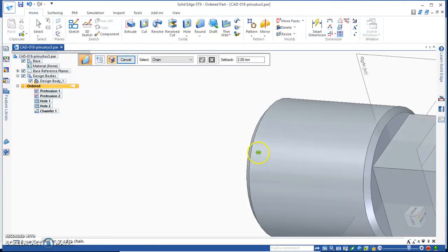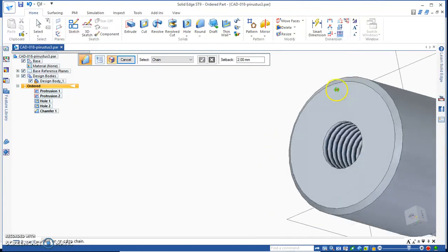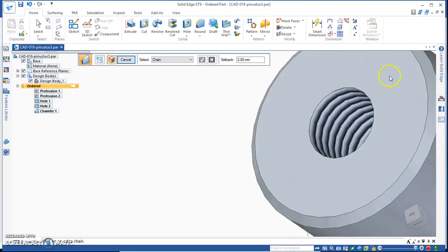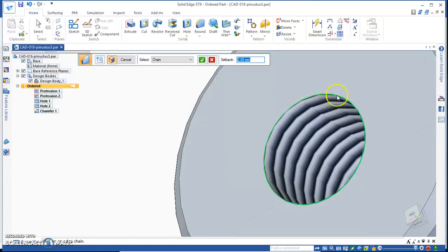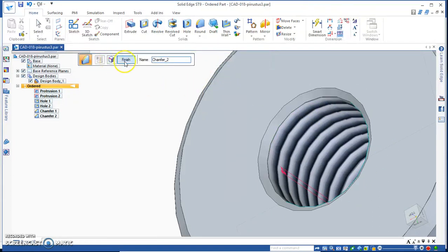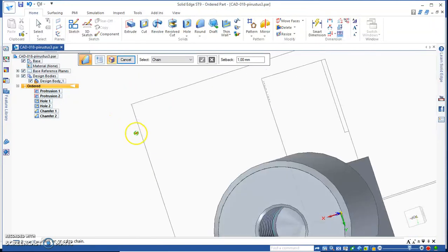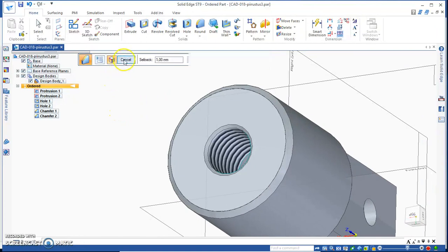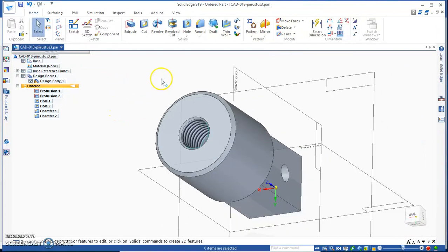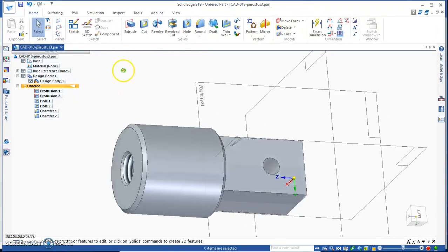and finish. And actually, if I look this hole, if you make this kind of thread hole, it's always good if you just set small chamfer to this corner, so it's easier to use. Okay.